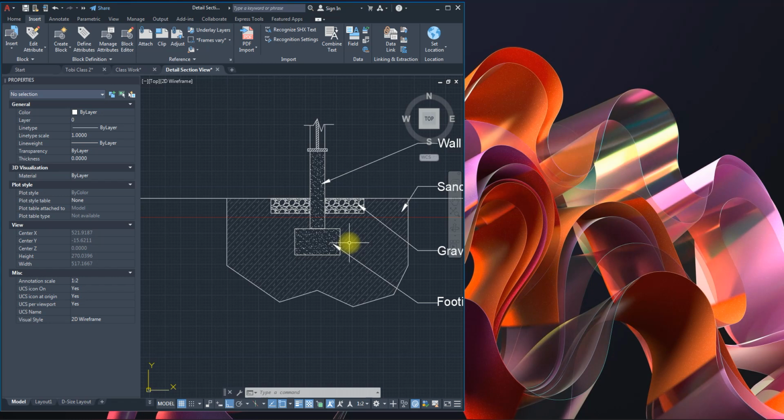So maybe, for instance, you are doing a schematic drawing, and you don't want to show the whole thing, so you have a PLC, for instance. Normally in the whole schematic drawing, you don't want to be showing the whole detailed information about the PLC. So you can create a separate drawing for the PLC that shows all your inputs and outputs, giving the ratings, everything. Then you can link that basic shape to the detail. So you can actually use that hyperlink for that purpose.